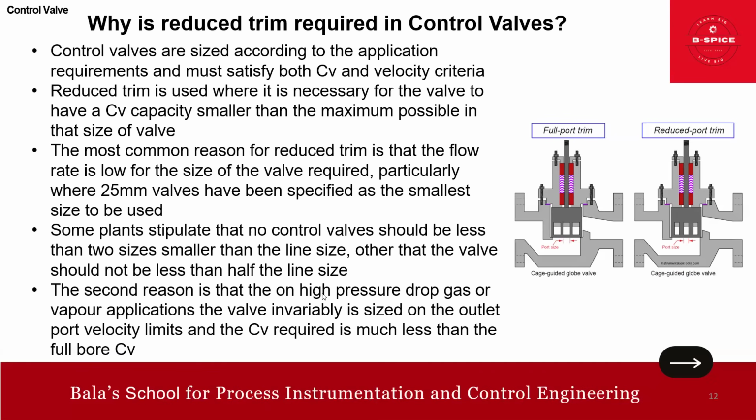Another reason is that on high pressure drop gas or vapor applications, the valve is invariably sized on the outlet port velocity limit. So the CV required is much less than the full bore CV. That is why we have this reduced port. I hope you got it, friends.